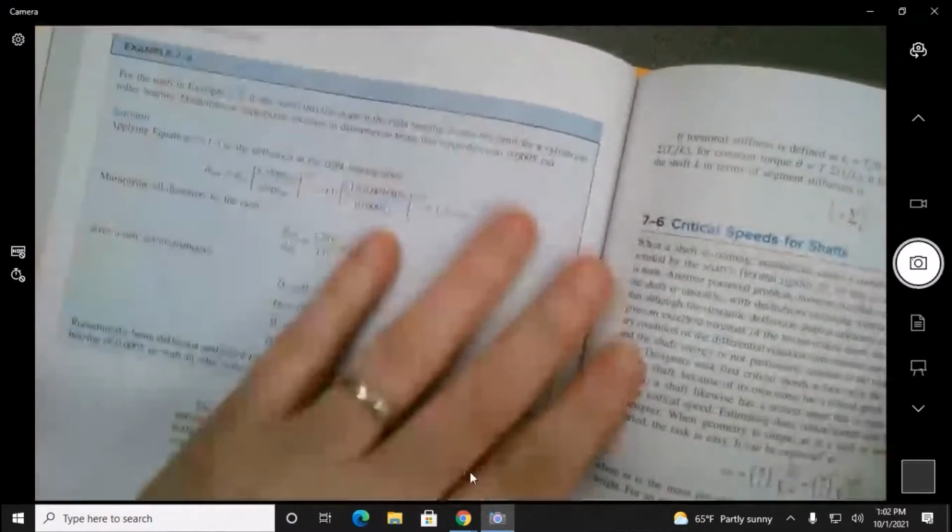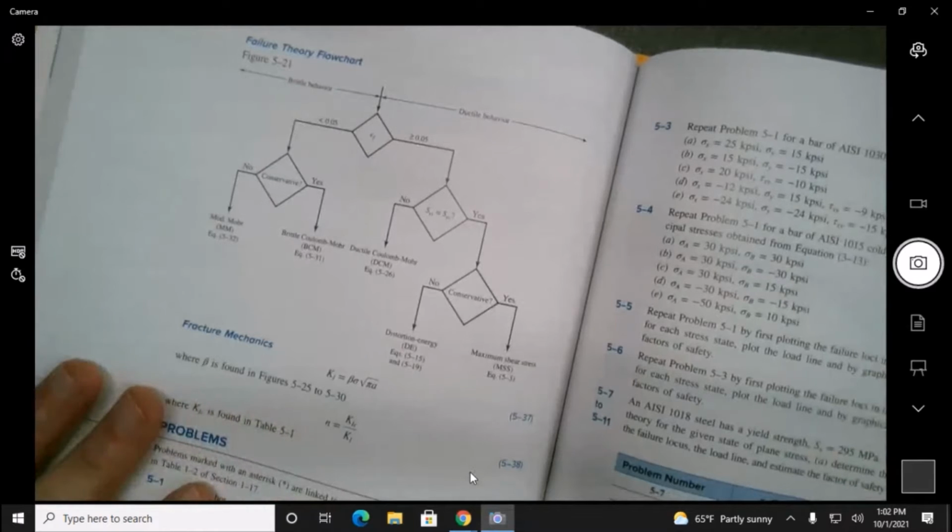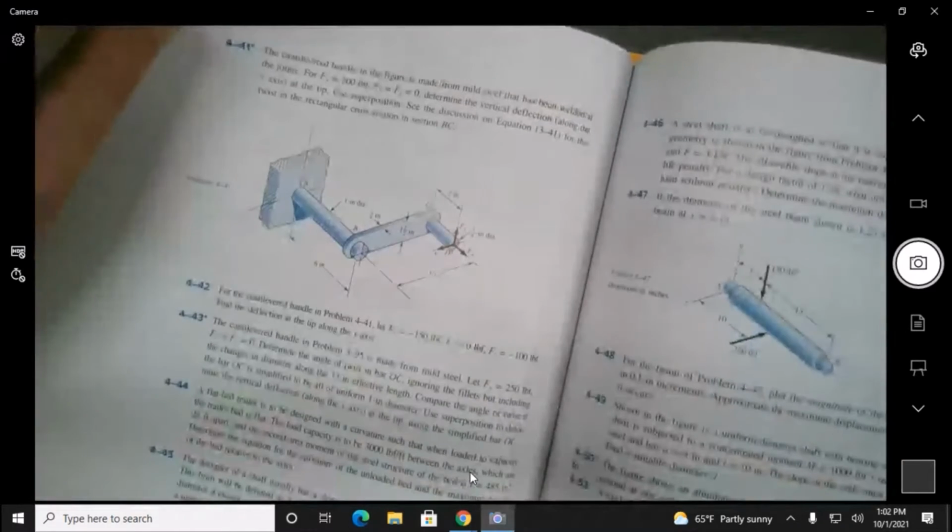Whether it's the Euler or the Johnson, if you're going to use effective lengths, use them all over the place and don't use any C's. If you're going to use the C, don't use any effective lengths. So when you use the effective length, then for L over K of 1, you wouldn't have a C in that equation where it's 2 pi squared. No, because you're just using regular L's. But if you are going to use effective length, use the effective lengths within that equation.